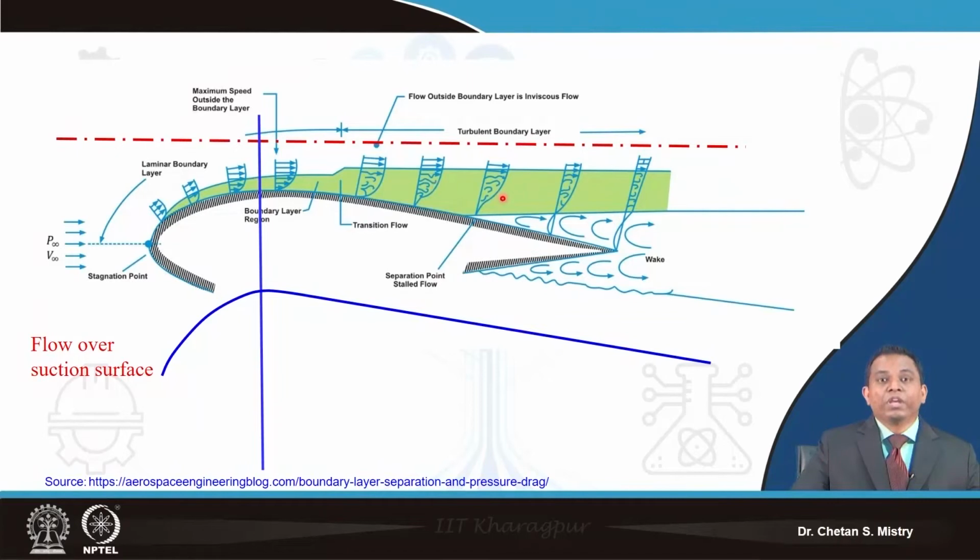When I say it is going under turbulent region, and when we are having this adverse pressure gradient because of the diffusing passage, at some distance on my suction surface I will be having the flow separation. That's what will be happening. So somewhere here is what is called the stall point, or we can say this is the inflection point, from where I will be having my flow separation.